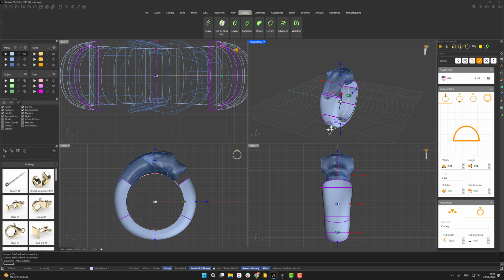When you are ready, remove the symmetry of the head. By pressing the Reflect command, select the model, and in the command bar, you can click Remove to get rid of the reflection. To unite the entire model, select all parts, then go to the Solid tab and use the Boolean Union command.